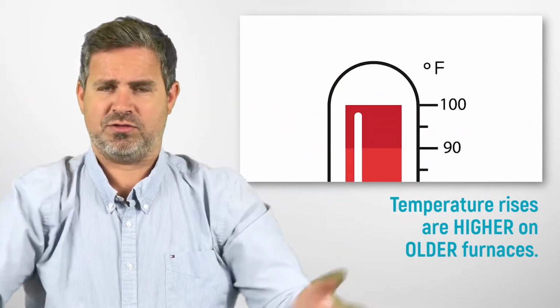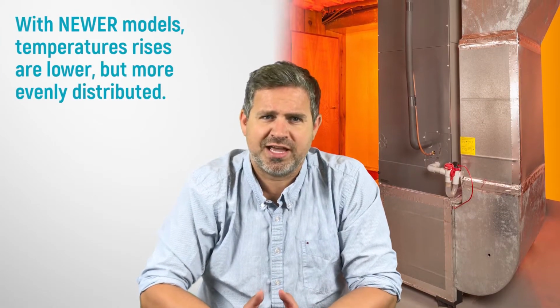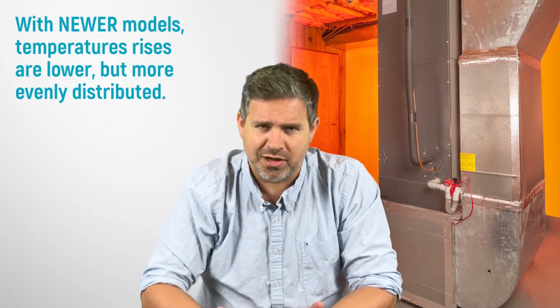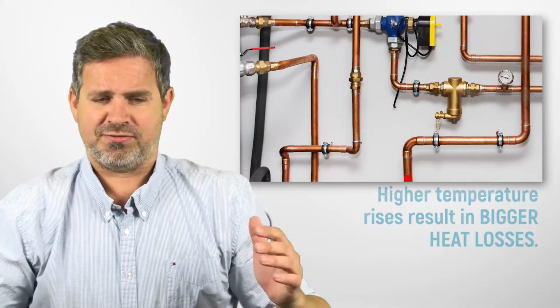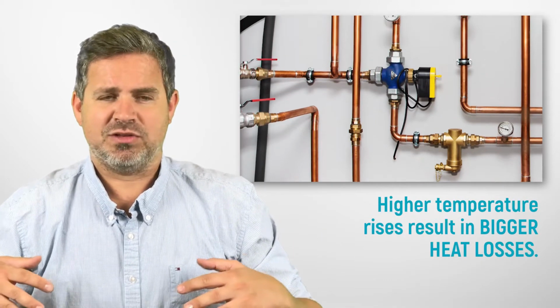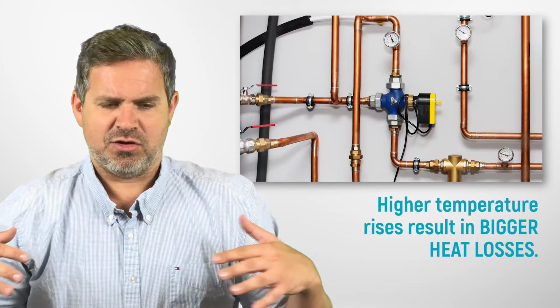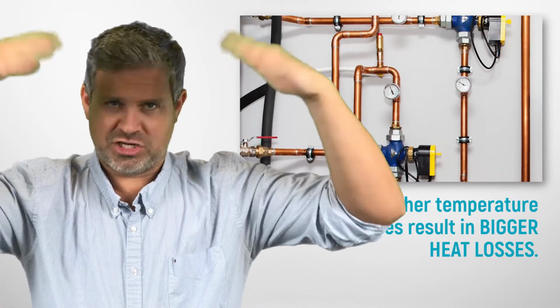And then it goes out through your house. So what they found over the years is, with newer furnaces, they actually have a lower temperature rise for forced air heating. The problem with the older systems, if the temperature rise is too high, the heat will just rise. It'll go to the top of the room. It'll make its way through the insulation, and you've lost it.